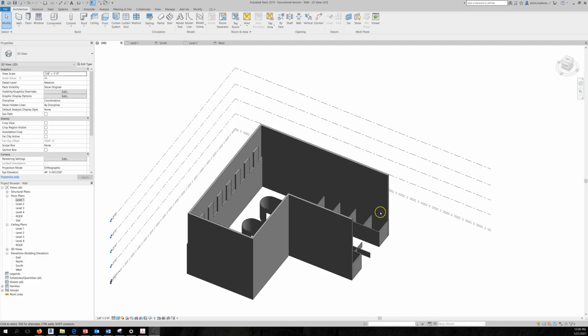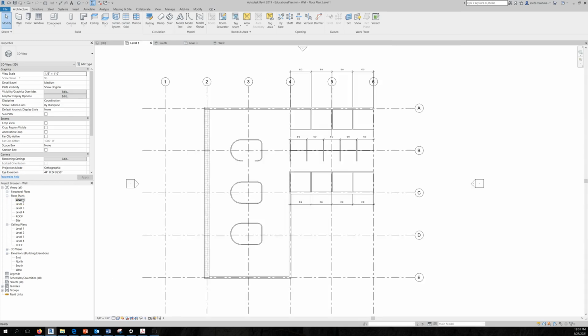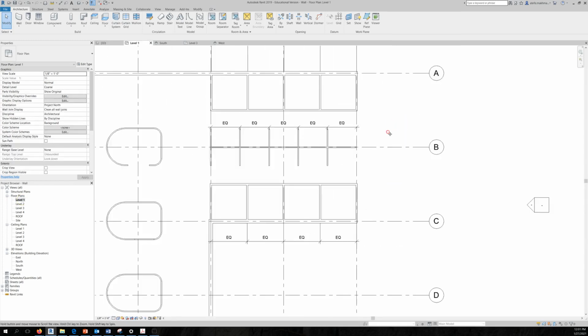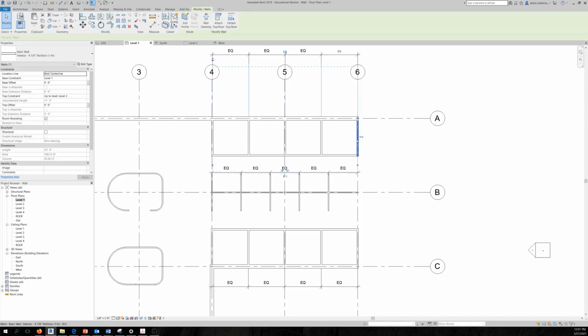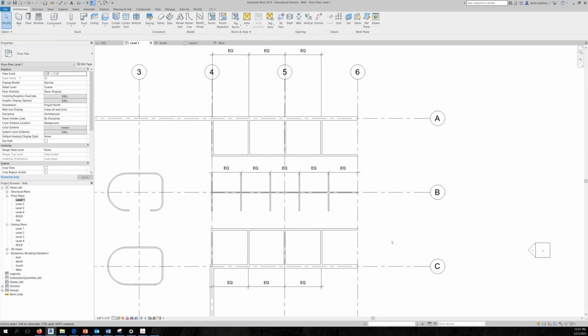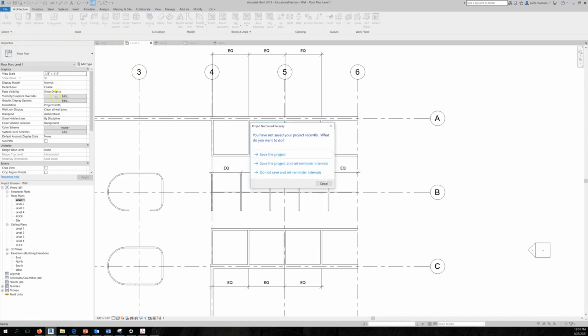Next, we want to add a curtain wall here where we have an opening. Actually, if we didn't have an opening here and if this was a wall, we could still embed a curtain wall. Let's see how that works, and then I would show you another way. Let's actually delete these two pieces. And then let's add a wall here.